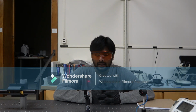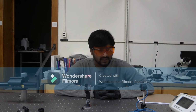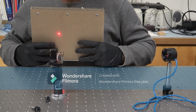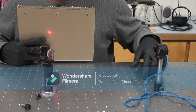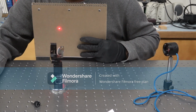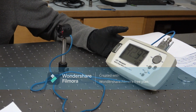Now we will demonstrate the planar beam splitter, which can also split the light into two different directions. So first you can see it directs the light in the straight direction and also towards me. So we need to measure both outputs and find out the ratio of it, how effectively it distributes the light into two directions. So first we can see in the straight direction it shows this numerical value.